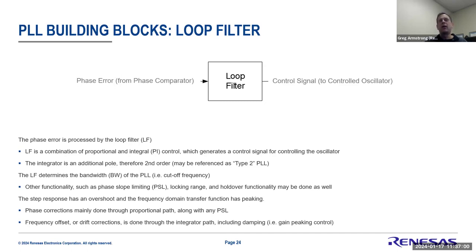So what if there's a lot of variation or noise, what we often call jitter, where maybe it's 10, then 15, then -5, then 0? All those numbers get fed into the loop filter, but averaged out, right? Over a time period, it may just spit out a 1 to the controller and say, hey, there's a lot of noise out there, but the reality is on average you're only off by about 1 nanosecond. So correct your clock 1 nanosecond and you'll be okay. This is basically the job of the loop filter.